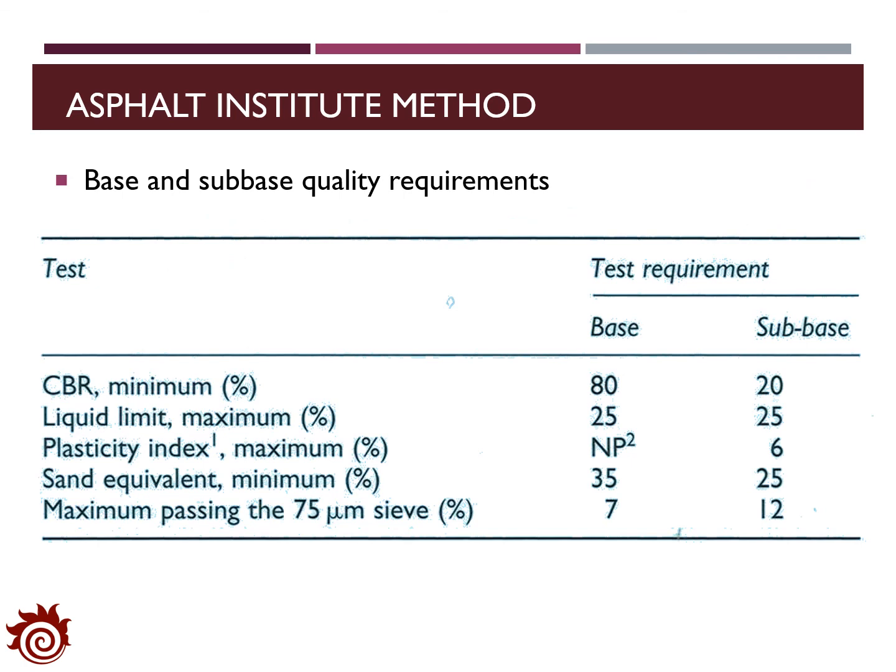In addition, there are some requirements about the materials for the base and subbase layers, including the minimum CBR values, the maximum liquid limit, the maximum plasticity index, the minimum sand equivalent, and the maximum percentage of particles passing the number 200 sieve. For example, for the base layer, the CBR value should be higher than 80, while for the subbase, it only needs to be higher than 20.